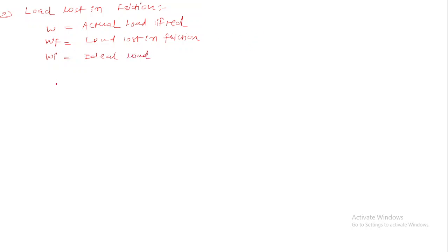So load lost in friction Wf is equal to ideal load Wi minus actual load W, because the actual load lifted will always be less than the ideal load. In the ideal load there is no friction, in the actual load there is friction. So Wf is equal to Wi minus W.